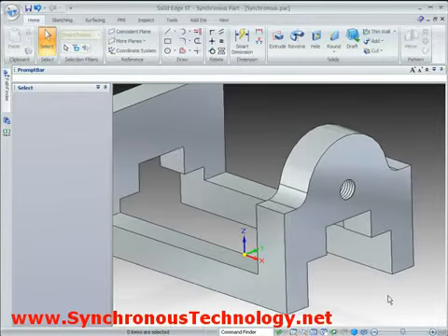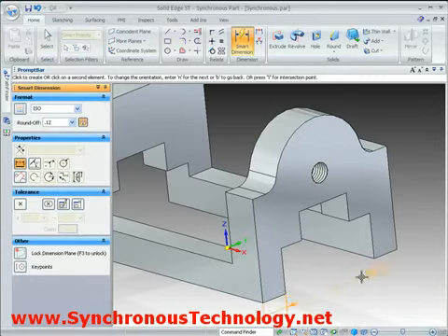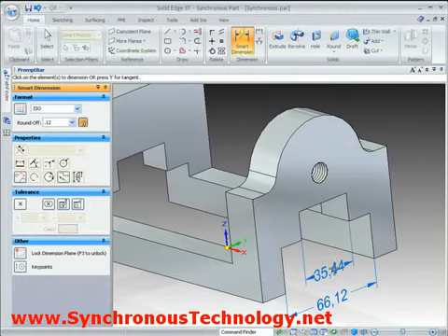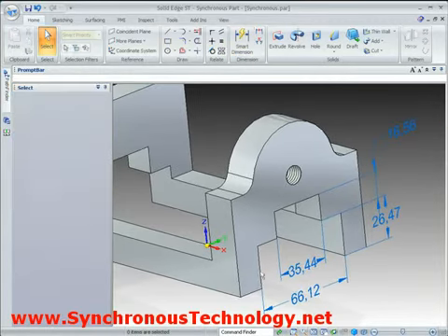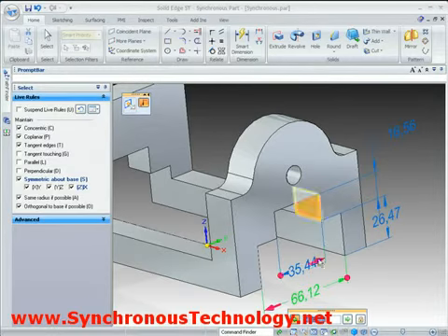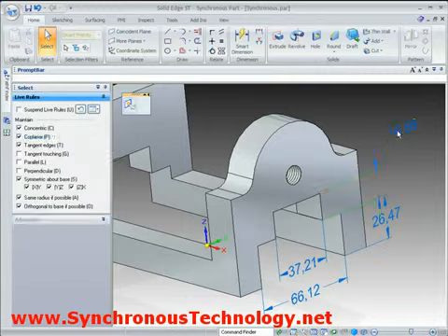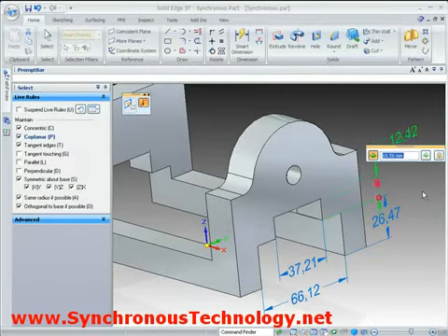If we require more control over the geometry, we can simply add PMI dimensions directly to the 3D model. There is no need to add them to the profile which originally created the feature. These dimensions can then be used to modify the model quickly and easily. The key thing with regard to these changes is that the model's history is not being recomputed, since changes are being handled locally. This means edits happen much faster.